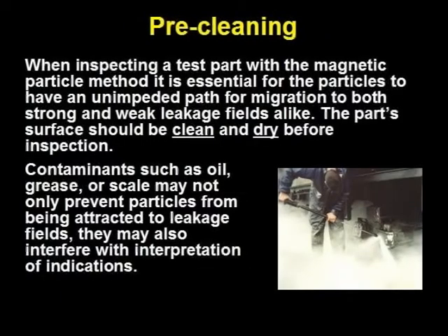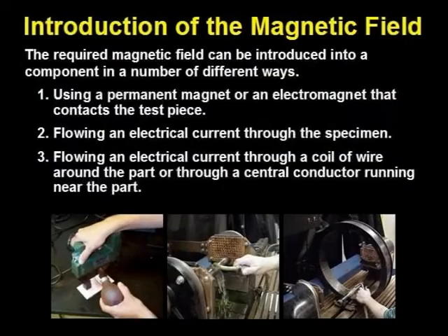Since the magnetic particles must be free to migrate over the surface of the test article, the part must be clean and dry prior to inspection. Thus, the part must be cleaned of contaminants such as oil and grease.